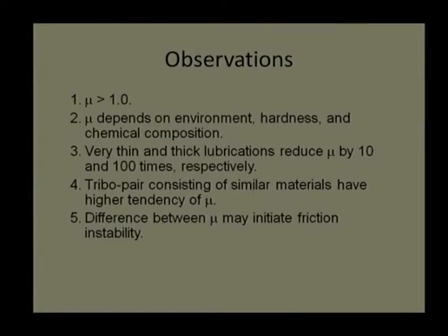It is an important topic, and it induces vibration, which we will deal with in the friction topic maybe in the 4th or 5th lecture. So, what are the observations overall? We say the coefficient of friction can be greater than 1.0, which is generally not written in a number of books.